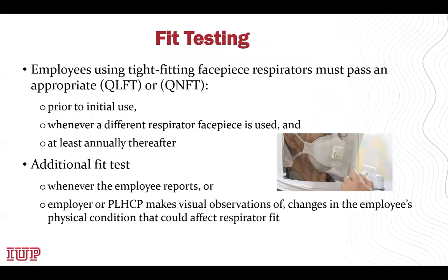Fit testing continued. Employees using a tight-fitting facepiece respirator must pass a qualitative or quantitative fit test prior to initial use, whenever a different respirator is used, and at least annually thereafter. An additional fit test must be conducted whenever an employee reports an issue, or the employer or PLHCP makes a visual observation of changes in the employee's physical condition that could affect the respirator fit.